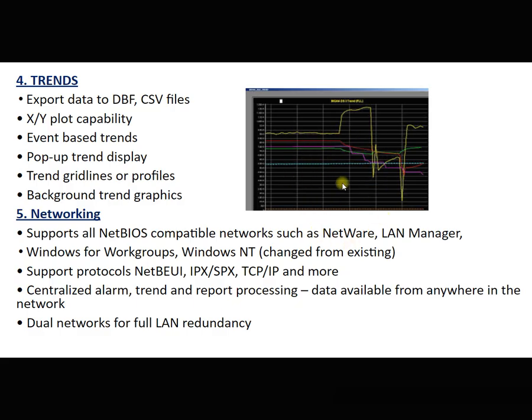All those data I can transfer to an Excel sheet, or to some open database connected. DBF means it's a database file. It may be SQL or Microsoft Access. I can transport there. Again, xy features are there, so according to the events it can generate, you can make some changes in that trends page also. I'll show you these things. You have two types of trends, real time and historical trends, that we'll get to know once we start this SCADA software. So this is about the trends.